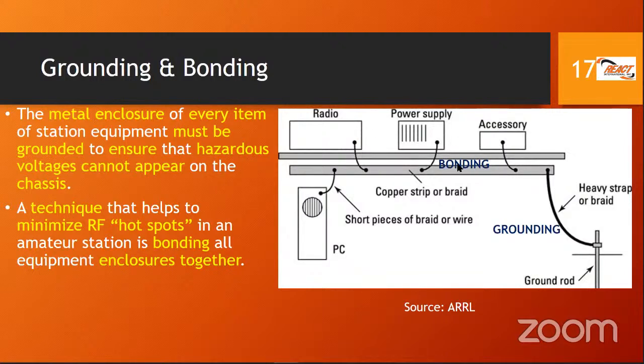Also, you need to bond the items as well. So you have grounding of it and you have bonding of it. The reason you want to bond it is to minimize what we call RF, or radio frequency, hotspots. So the solution to avoid RF hotspots is to bond all of the equipment.